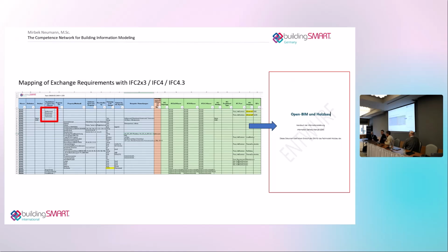You go to assembly, so it's when it was installed, when it was fabricated, was it fabricated on site, or was it fabricated in the factory. So you can definitely define everything. What you cannot define, maybe some new properties, are left with question marks. So you have to check, and the mapping in IFC is the most essential thing.